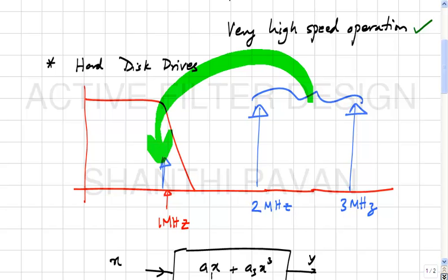So this obviously is a problem because we didn't know that the filter was nonlinear, we take everything coming out of the filter as being the desired signal, we now see that tones which are outside the filter bandwidth can cause components within the signal bandwidth because of nonlinearities in the filter.